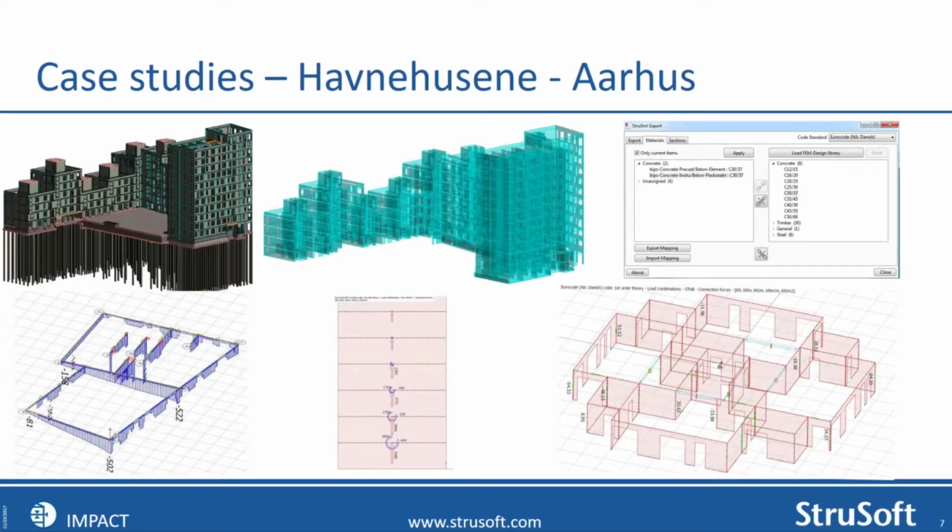And then another feature they found out. Now they could test the forces in the joints, the shear force in the joints, the vertical shear force in the joints. Whether you have the regular stirrups or you have the wire box, they will have two different load carrying capacities, and this is something we need to be aware of. If we want to link this wall to this wall because we need its weight in the stability system, we need to make sure that this load is less than the capacity. So suddenly they got full overview of all their loads in the joints as well.